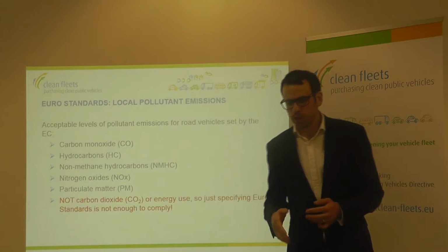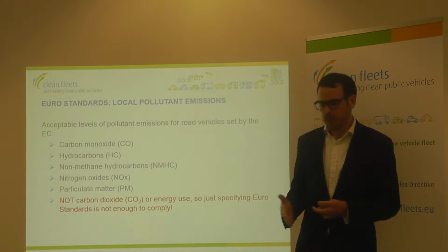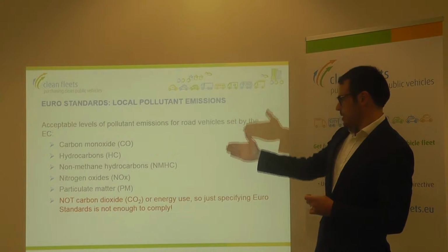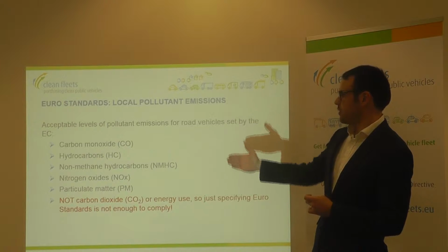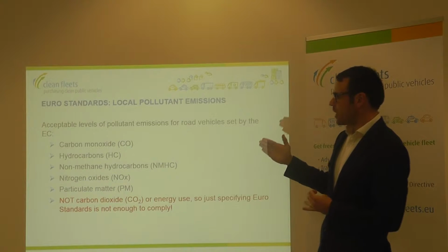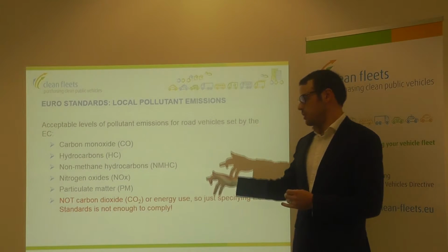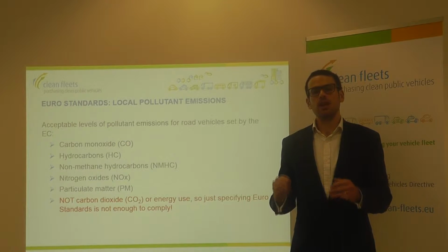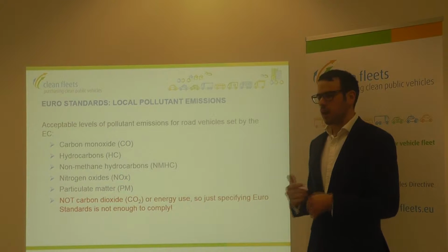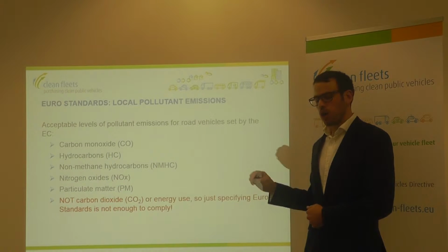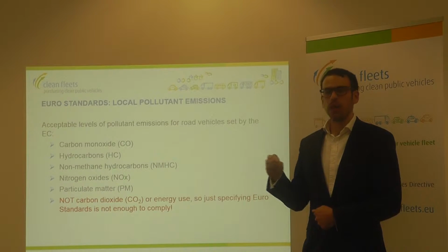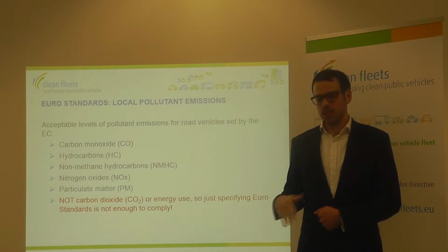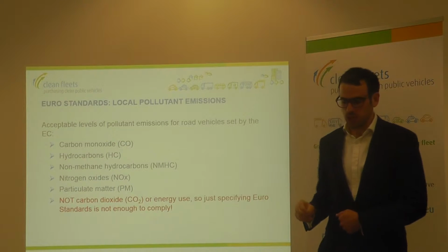Now, what the Euro standards do measure is these 5 different emissions. However, they do not measure CO2. Carbon dioxide is not part of the Euro standards. Carbon dioxide is a climate change associated emission, not a local air pollution emission. And the Euro standards are only designed to tackle local air pollutants.